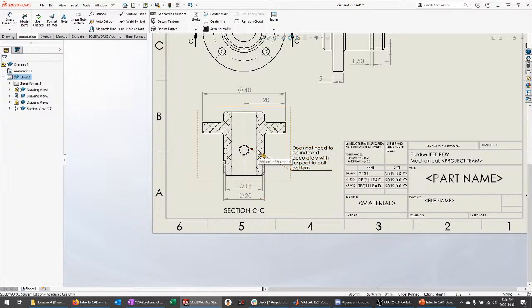Part of the purpose of GD&T in general is, like I said, we're not going to get into the specifics of how to do that, but one of the goals of GD&T is to reduce the number of notes that are actually necessary on a drawing. Particularly handy if the people manufacturing a part don't speak the same language.